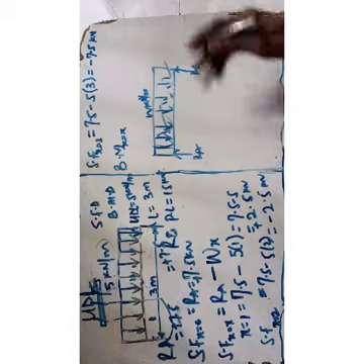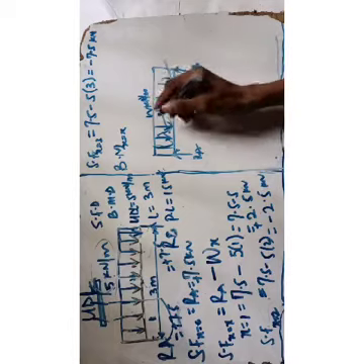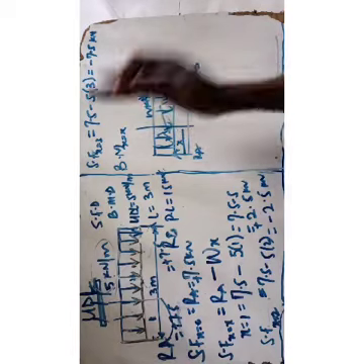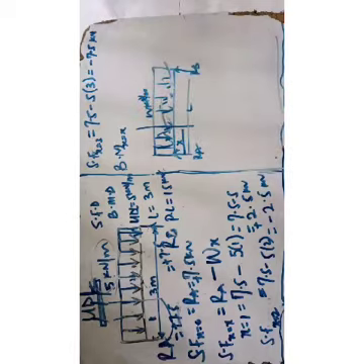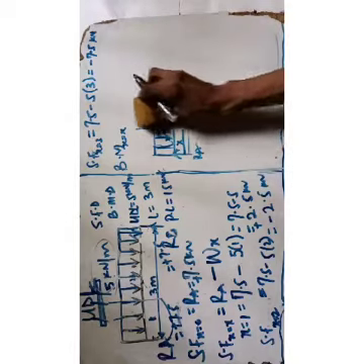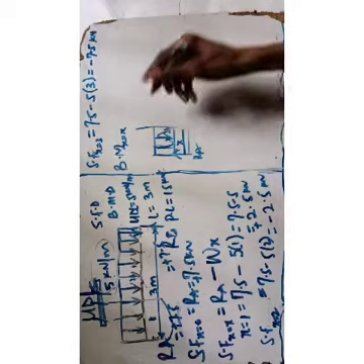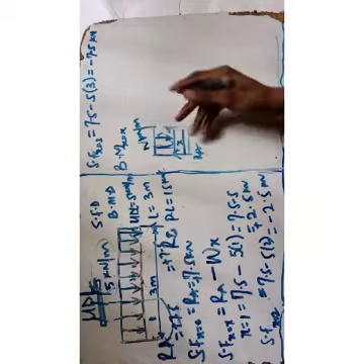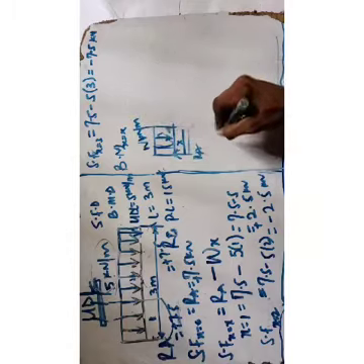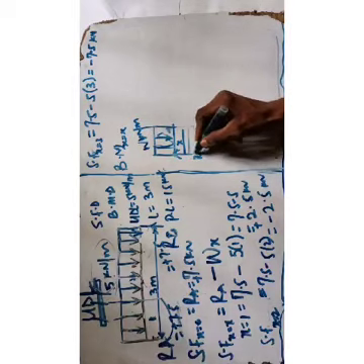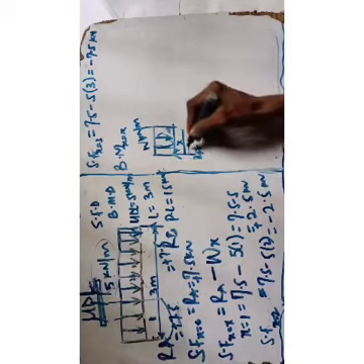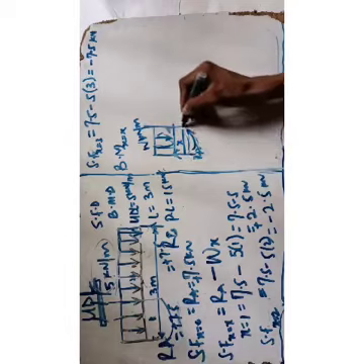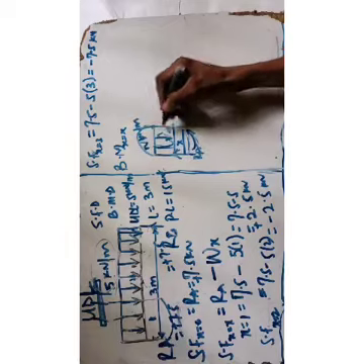So to take the bending moment, let's say we want to cross section this, and let's say for each point x. So let's say here the total length is L, and for just ordinary this point x, I want to bring this diagram out. So if I bring this diagram out, I'm going to have something like this, okay? The same weight is the one acting here, okay? That is kilonewton per meter. First thing, I will convert this to point load. So to take the moment, that will be the RA, what it's covering. RA it's covering, taking clockwise and anti-clockwise, right? So I want to take moment about this point now, right? That is RA times x, and the weight will come back times x, okay? Times the point it's covering.